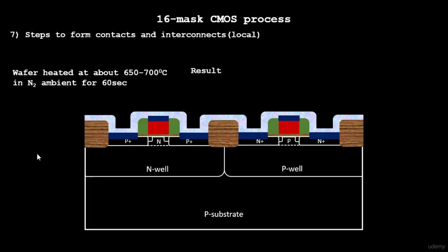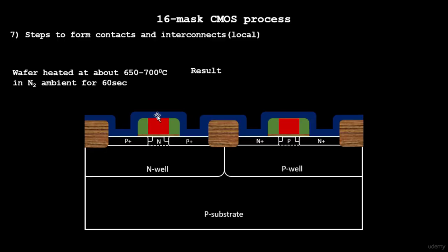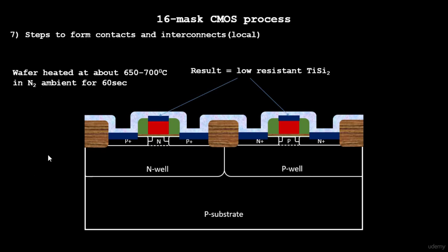In the further videos, when we create the source and drain, the source and drain implantation will affect only this area, and hence this particular portion of your lightly doped drain is kept intact. Similarly, when we do an N plus implantation over here, the N plus implant will be only in this area and this area, and the sidewall spacers help to maintain the N minus implant over here. Hence we get the N plus, N minus, and P doping profile that we expect. So we'll stop at this point, and in the next video we'll look into how the source and drain formation happens.